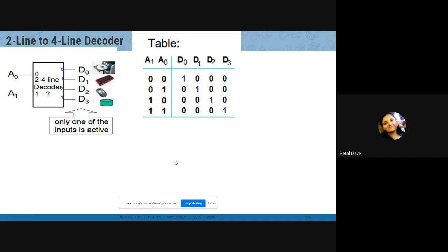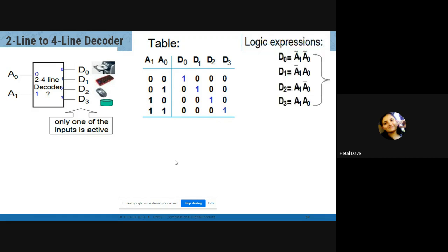Now after the truth table, what is the next step? Boolean equation. How many equations can be made? Yes, the number of Boolean equations is equal to the number of outputs. Total 4 outputs, D0, D1, D2 and D3. So 4 equations. D0 is A1 bar A0 bar, D1 is A1 bar A0, D2...